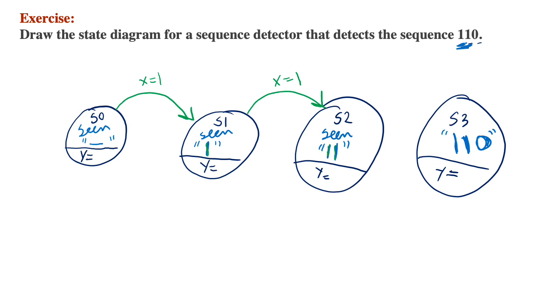When we're in state 2 and we receive the last bit of the sequence, which is 0, we're going to transition from state 2 to state 3. What I'm going to write next is the output bits in each state. We only have one output, but I need to specify it inside each state since this is a Moore machine design.